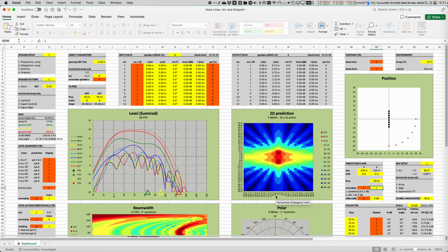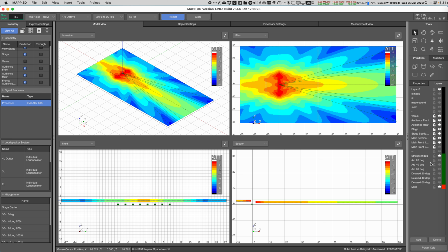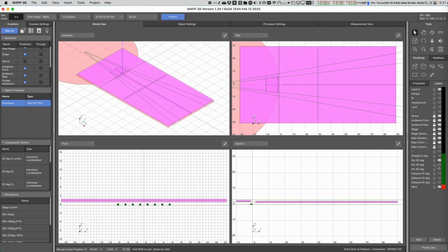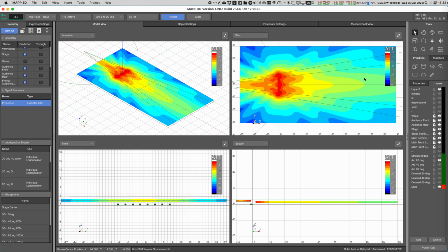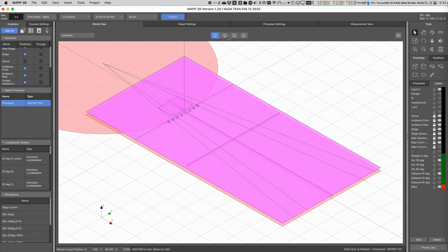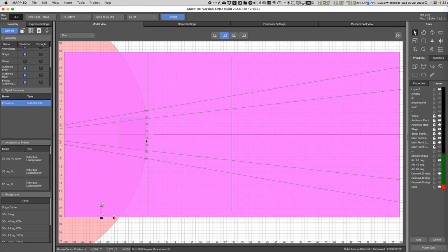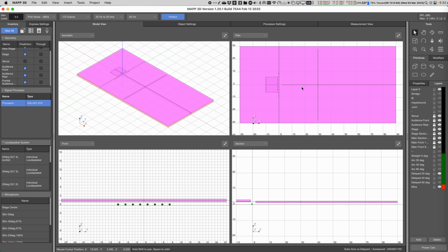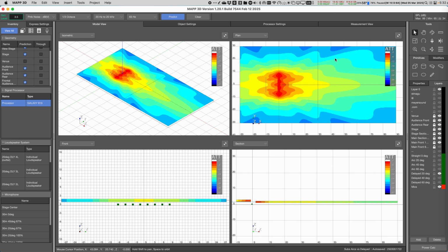So this means that in reality, the maximum frequency that I will play is 90 Hertz, so this will not be lateral summation. So if we try to compare here, then the 20 degree system with arc shape, we have here, you can see wider in the front, narrow in the back. And if we want to compare with electronic delays, you can see that with the electronic delays, the only thing that is happening is that the speakers are being moved from the arc position to the front. So let me take this out, come back here all together, and now you will see that it's wide in the front and it's wide in the back.